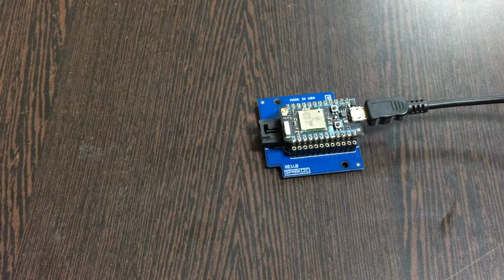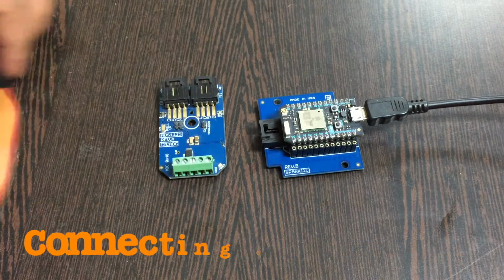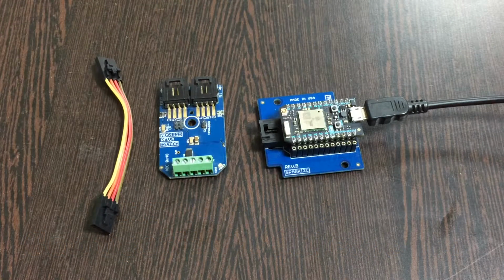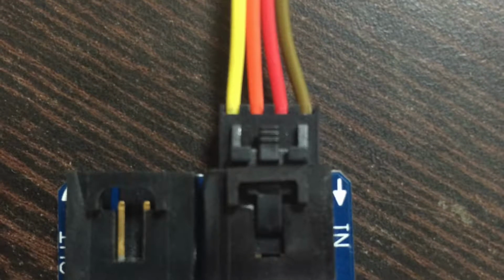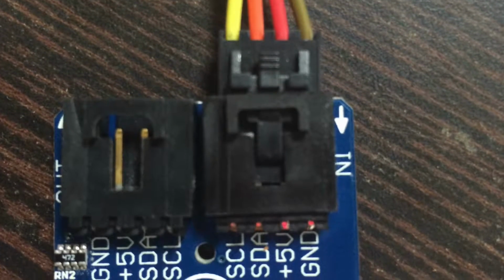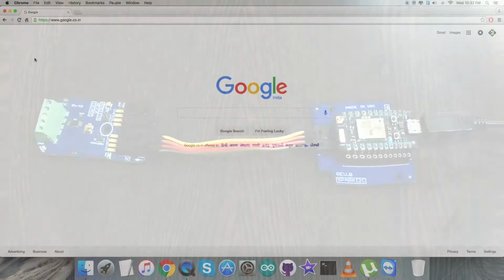Now what we require is our sensor, that is ADS1115, and this here is a connecting cable. Now make the connection between the sensor and the cable, and make sure that the brown wire of the cable should be connected to the ground terminal of the sensor, and the same rule has to be applied to the I2C shield. So we are done with all the connections we need. Now what we require is to have a look over the code.